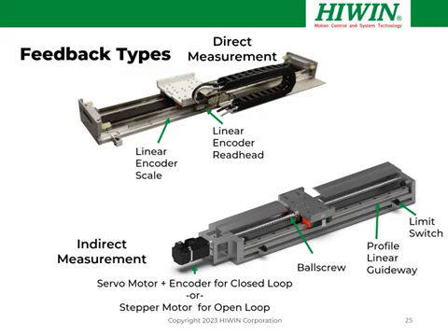What you can do next is you can add a servo motor instead. Take the stepper off and put a servo motor with a motor-mounted encoder on the back. Now you've got what's called a closed loop system with feedback, and that will give you higher dynamic performance and also better accuracy, because now you're measuring. But you're still only measuring where the motor shaft is because it's coupled to the motor. You will have wind-up and deflections, and you're inferring or indirectly measuring where your payload is.